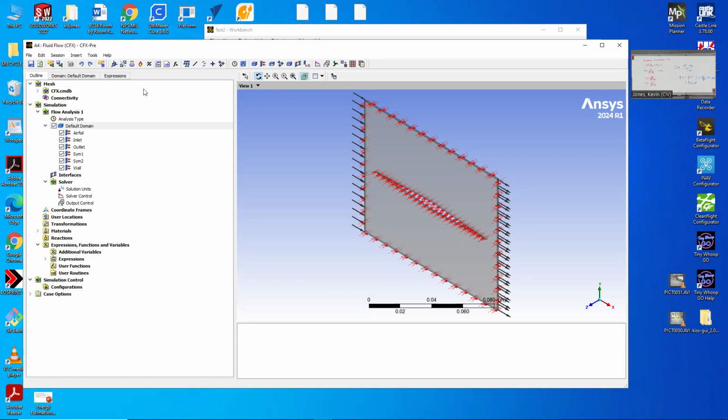And then, if you're trying to be precise, we'd probably like to carry the calculations up in front of the nozzle throat, and so start with subsonic and go through the throat to turn supersonic, because the boundary layer is already growing back there. So I don't know. Yeah, it can be done, but for our purposes.